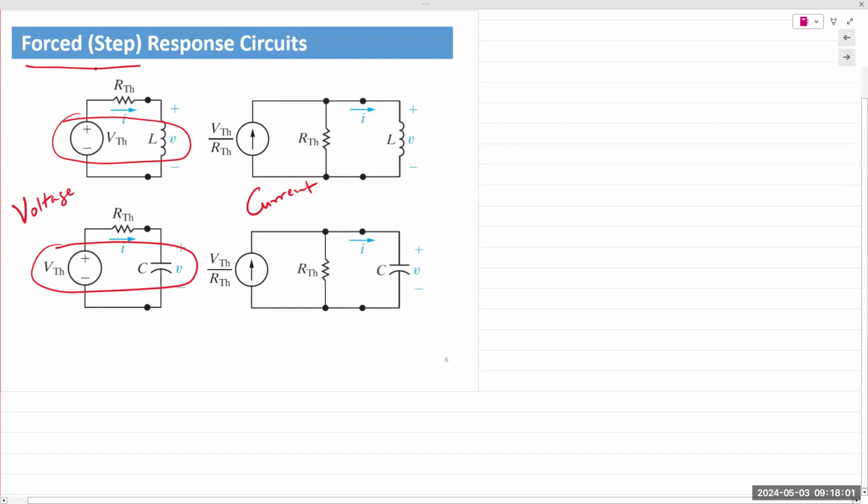This right here shows you the application of the Thevenin and Norton equivalent circuits. If you have a capacitor or inductor connected to a circuit, similar to a resistor, if we need to find the voltage or current that is being applied to that component, then we need to find the Thevenin or Norton equivalent circuits for that component. Okay. But again, this is a non-E major class. So again, we will look at circuits, but nothing too complicated in terms of determining like a Thevenin or Norton equivalent.